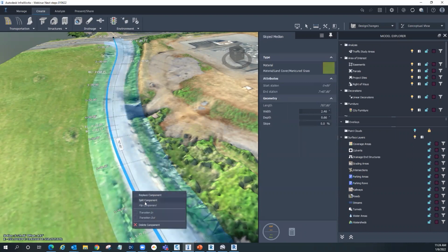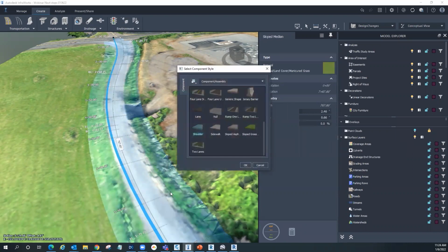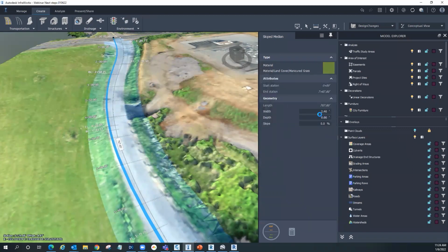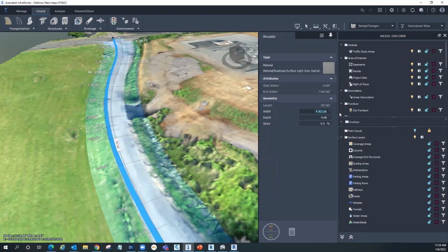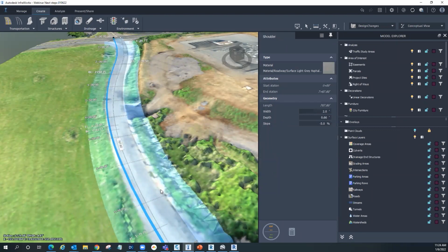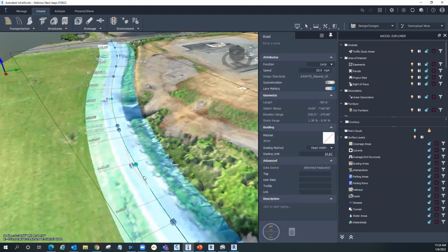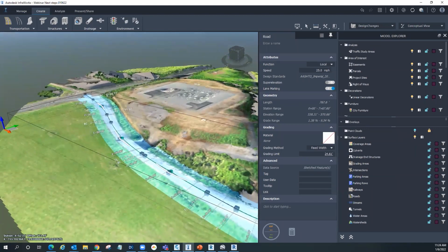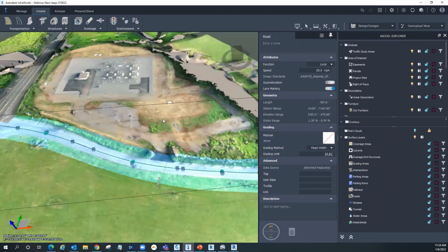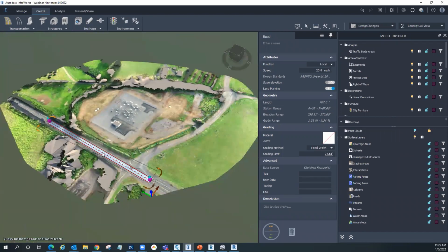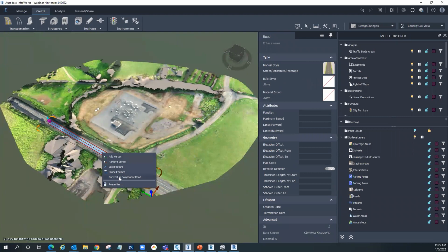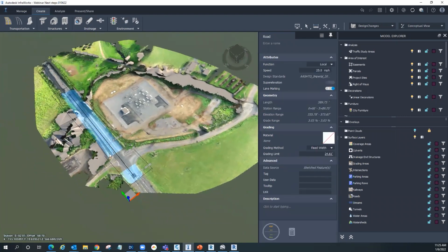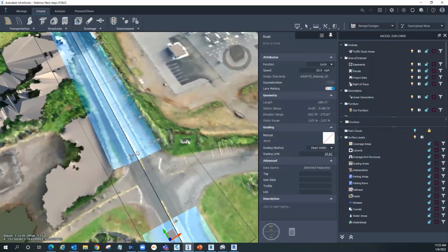And let's go and change that other replace component with shoulder. Make this 2-foot. Okay, so we kind of have a road in here with component road. Let's go and add the highway one. So we'll go and select this. We'll go and make this a component road. I'm just doing right click to do that. Okay. And let's go ahead and make some adjustments here.